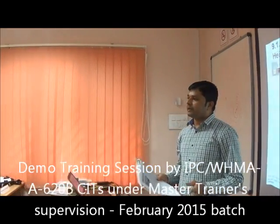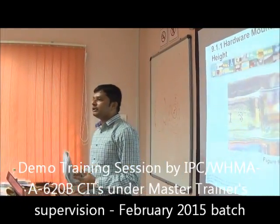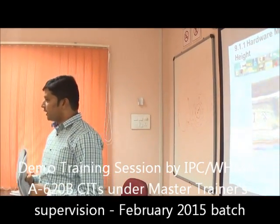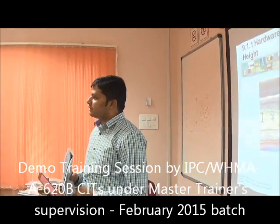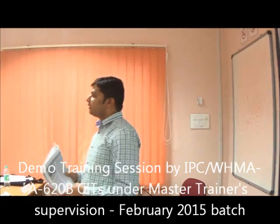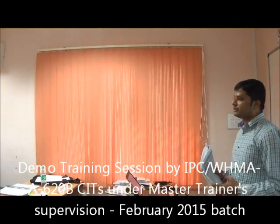So basically in the military and defense, we prefer only circular connectors because it's compact in nature and lightweight. Second, it will withstand the vibrations, and third, it will withstand severe environmental conditions.